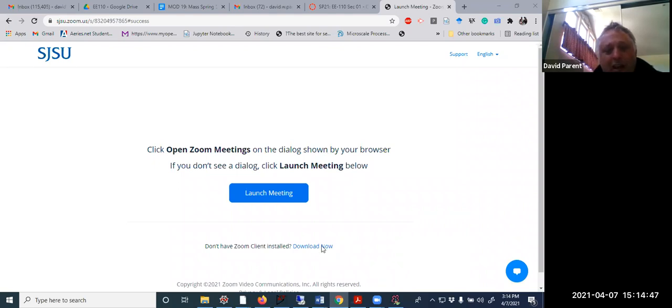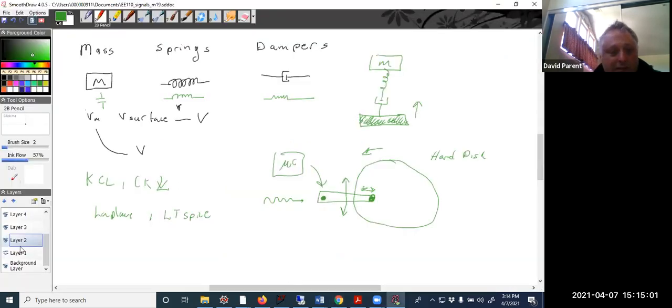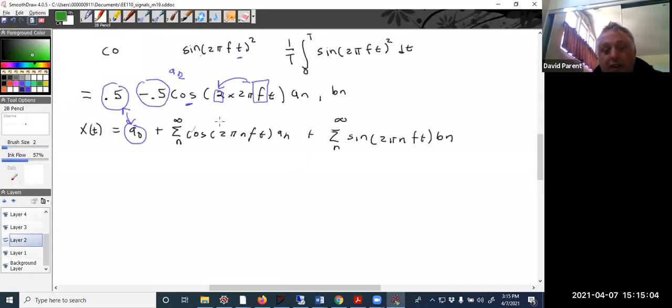How do you find? Oh, so, hey Andrew, sorry, I just saw your question there. How do you find the generic AN? Sorry, everybody. I didn't see that question. So in this case, you don't, because this transforms into this identity. There is only one term, and it's doubled. The frequency is doubled, and now you have a DC offset. But there are no sum of signs. So there's nothing generic about it. There's only one there, right? There's only one frequency created, and it's double the original frequency.